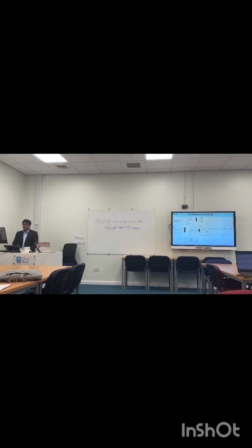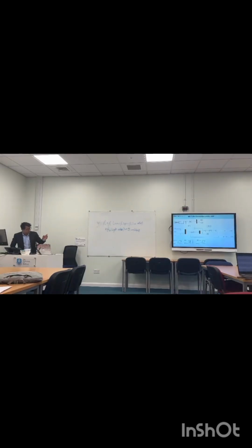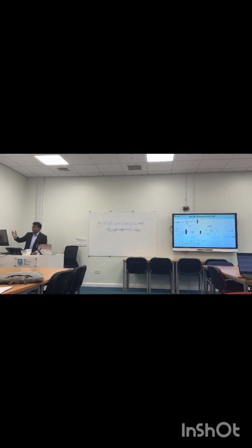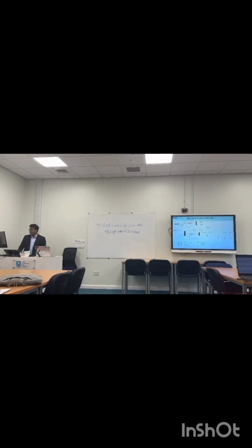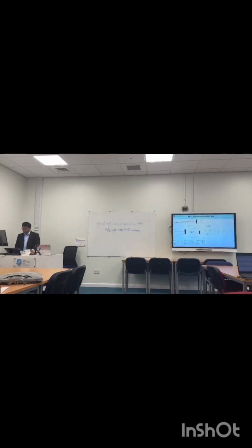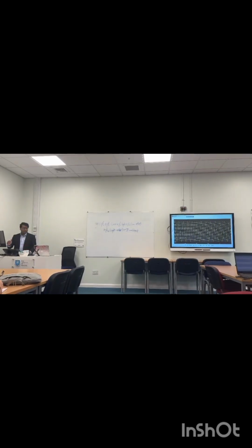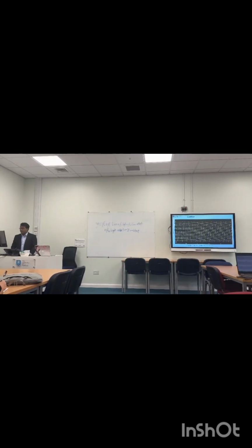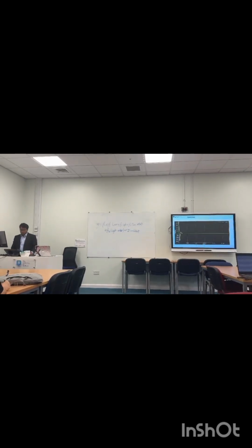And this is the PLL of synchronous reference frame, where I used, I think that one is clear much better. So it's ABC to DQ transformation. Then, as I mentioned here, are the D and Q voltages. Then the D and Q voltages are feedback controlled, and I check the active power and reactive power. If I check it on the oscilloscope, this is the 120-degree phase shift of my input voltages. Then this is the oscillator output, and it's clearly showing that the oscillator is working.